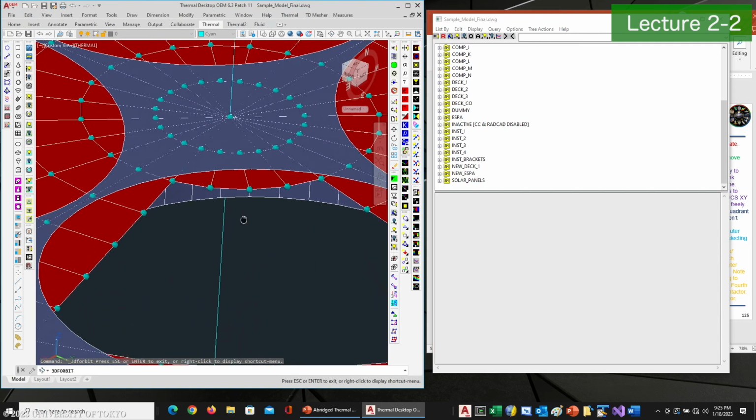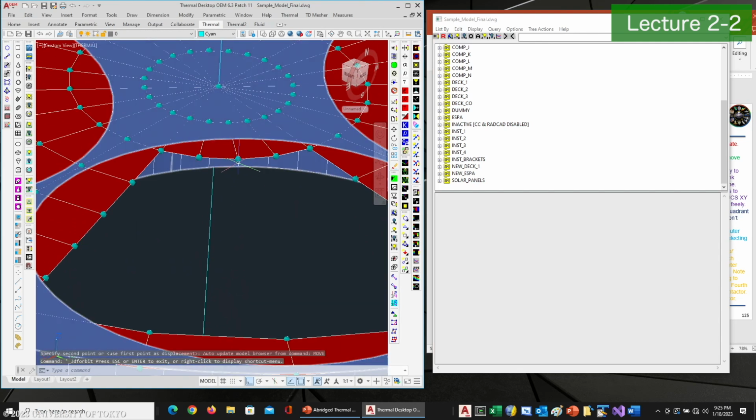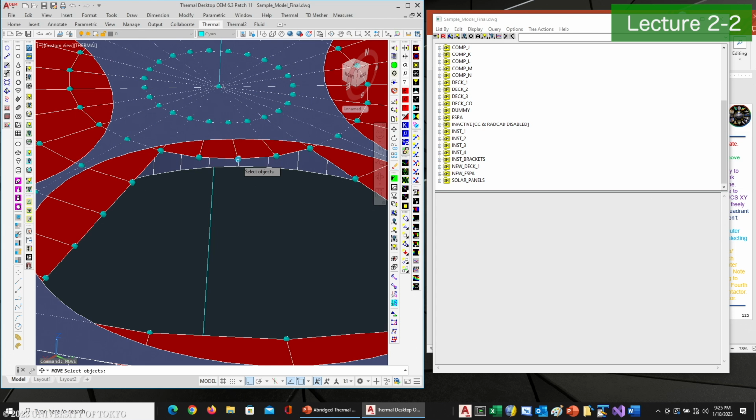And so now you can see that I can start taking and moving some of these nodes. So let's actually use here and then say nearest. So similar to those grips for the surfaces that we saw, nodes have a grip. So if you kind of hover in the middle, it sort of snaps to it, and you can do move node and then do near.